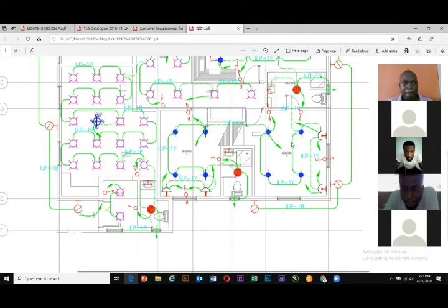So quickly, take down these factors, take down this value. Our E for this bedroom, we are going to assume 200 lux. Now, our length for the room is 4 meters. The width, 3 meters. Are we there?